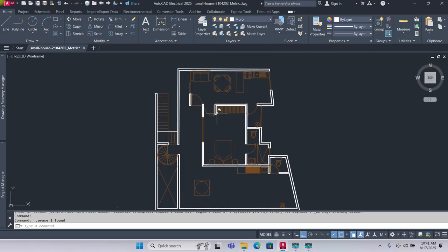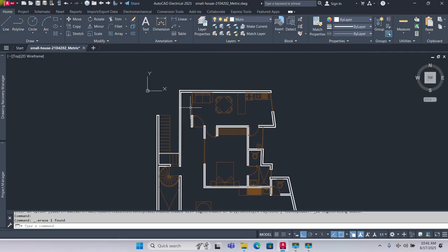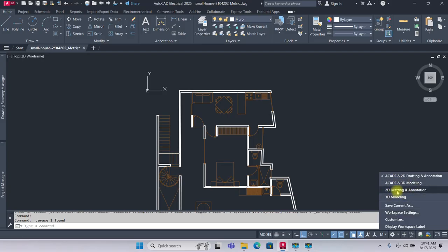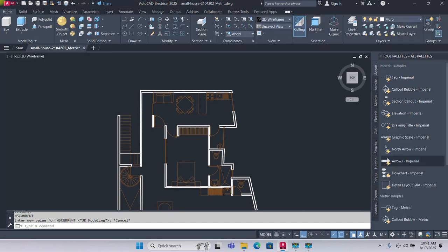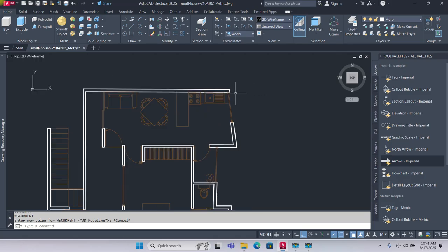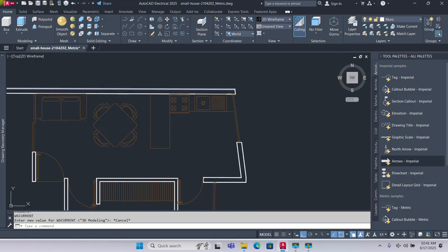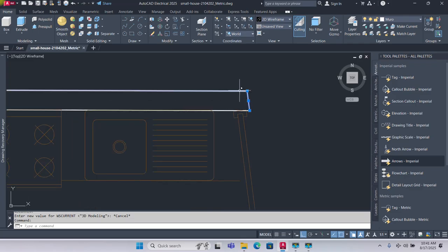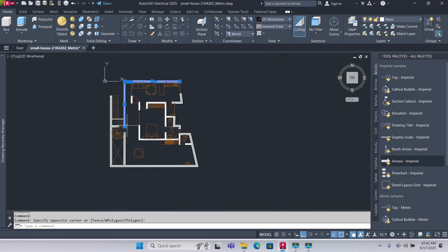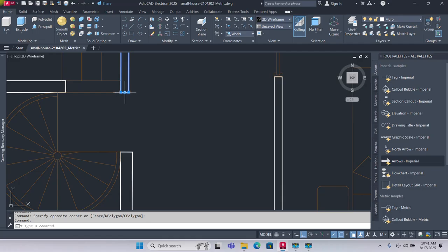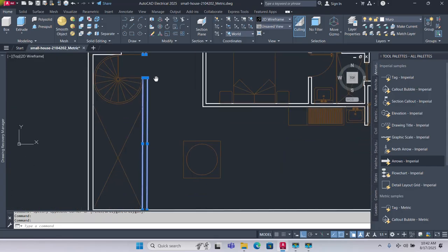So now that I have this completed, the next thing I want to do is go into my 3D workspace. Just click here, go into 3D modeling. Once I go into my 3D modeling, right now if I select this line, it will be selecting them as separate objects. I really want to make this work easy for myself. So I'll select all these white lines like so. I'm going to join them to become one object, so they will be seen as just one object, like a polyline.